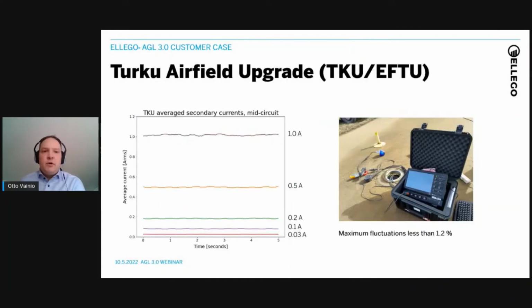And what it looks like from the electrical side, this same taxiway edge circuit, the approximate knowledge I have from that is roughly 4 kilometers of primary cabling and quite a bit of secondary cabling as well, especially because it goes to the sign. Some of the fixtures, of course, don't have that much of secondary cabling because they sit on top of the cans directly.